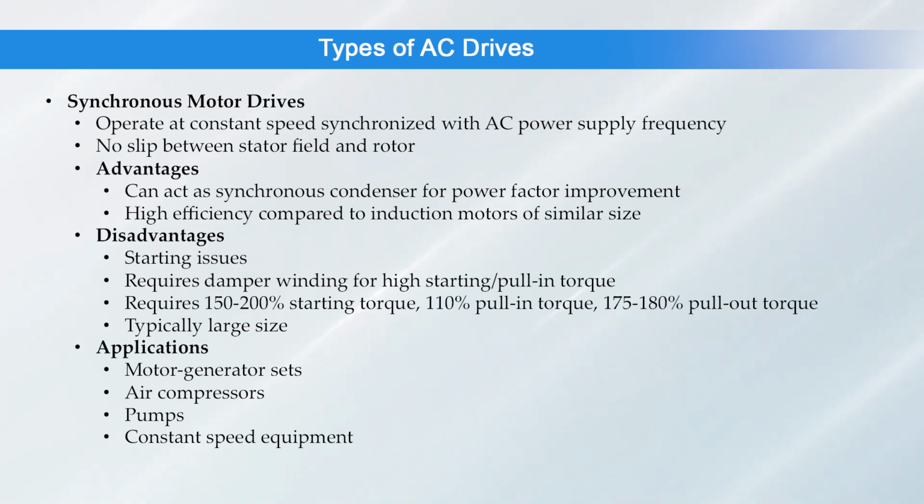Synchronous motors though have some disadvantages also. The starting problems are faced here. A damper winding is required. If high starting and high pull-in torque is required, a double cage damper winding is used.